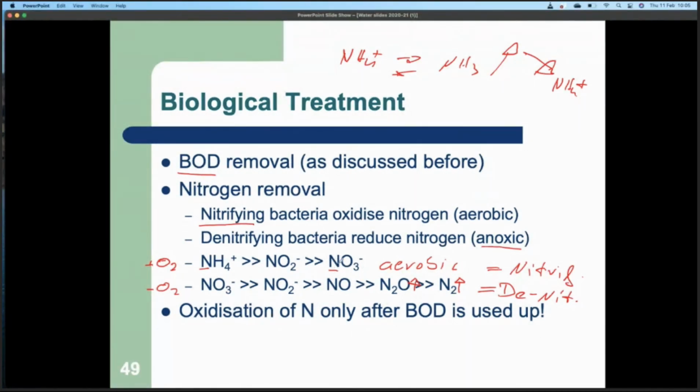And all that could mean in a treatment works is that you have a tank where the water is being treated, and you have the blower on for an hour and a half, and then you switch the blower off for half an hour, and then all the oxygen is being consumed, and all of a sudden the bacteria find themselves without oxygen, and the facultative bacteria will then switch their respiration from oxygen to nitrate, like I said before, and they will use nitrogenous oxygen for the respiration, and thereby denitrify.